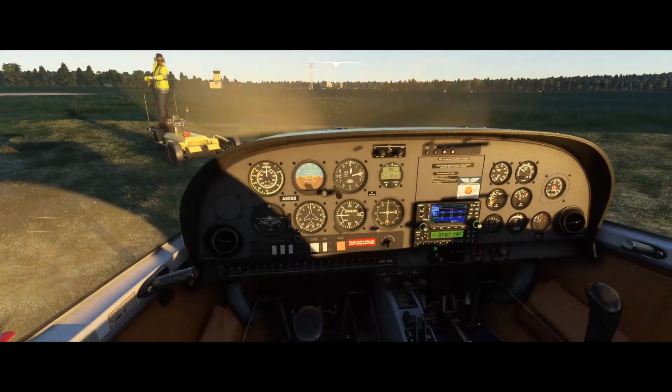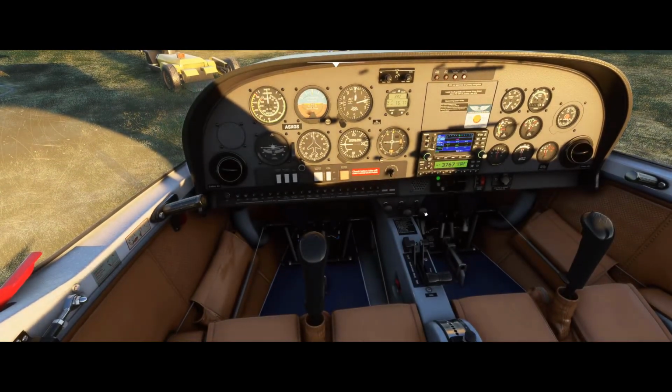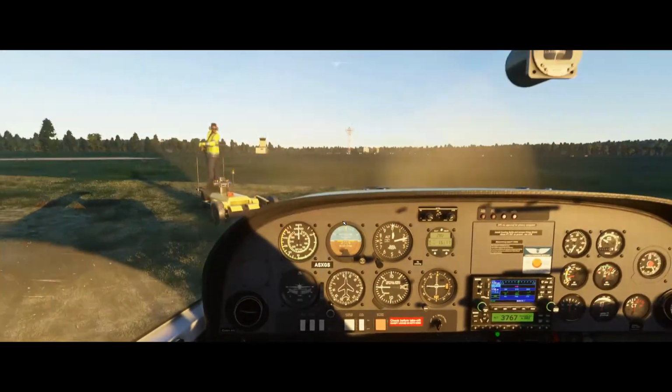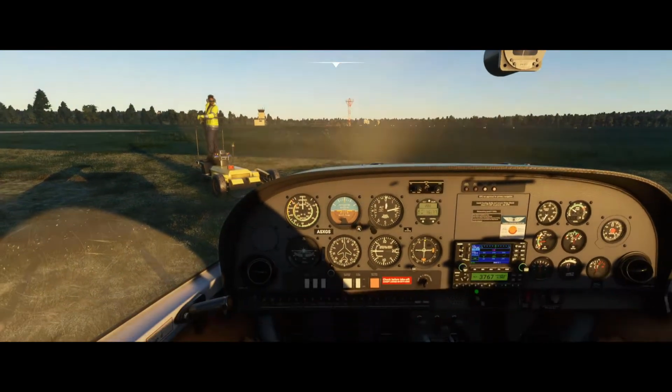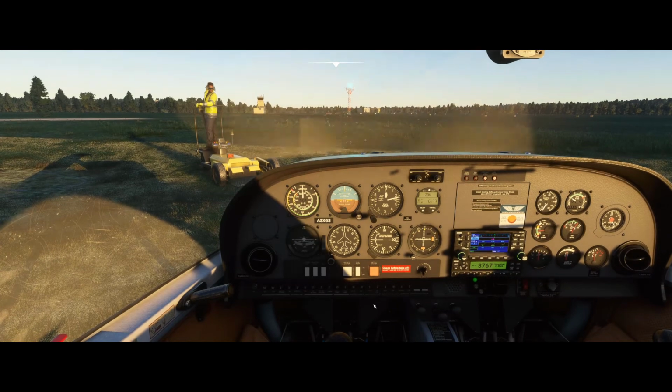Now we're going to taxi over to the runway. So we just pull the parking brake, release it. See that the pedals come back. The way to steer the Katana is it's differential. So if you press on the right pedal, it will go to the right in terms of the brake, and if you brake with your left foot, it will go to the left.